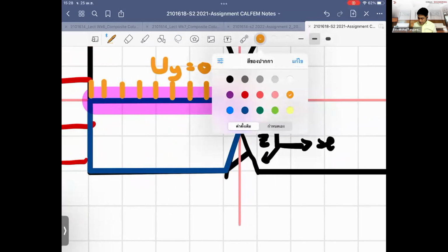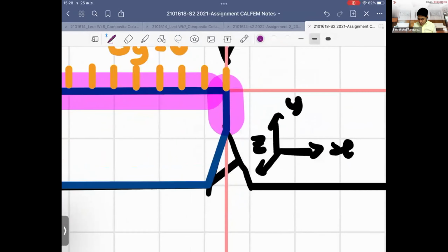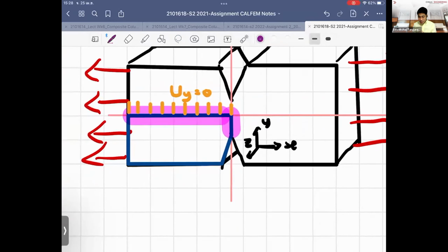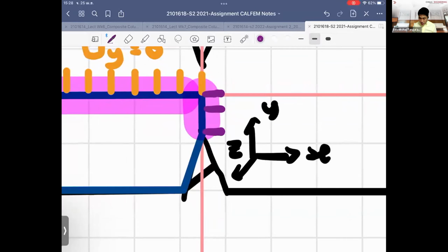On the other side, it also comes with another boundary condition, where it is sharing a mirror image about the y-axis. So we can imply that along the line here, except up to the crack, we restrain the displacement about the y-axis, or ux has to be equal to 0, so that the double symmetry can be applied.